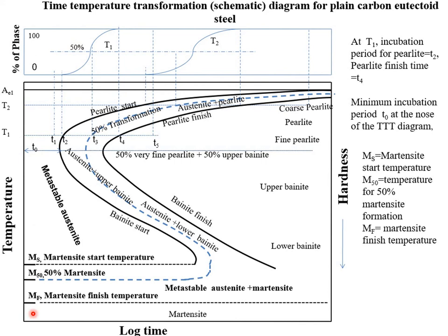For example, if you are getting pearlite at a rate of 10 degrees per minute, or let's suppose 5 degrees per minute, then for martensite you will want a cooling rate of 150 degrees per minute, or say 200 or 250 degrees centigrade per minute, in order to achieve proper martensite.